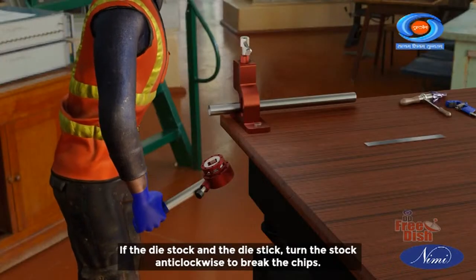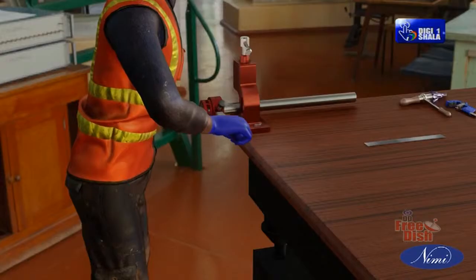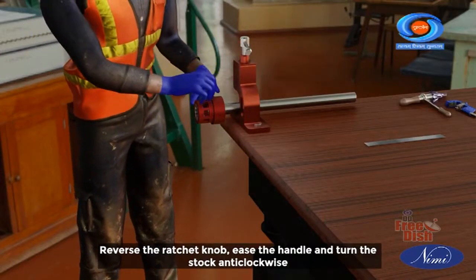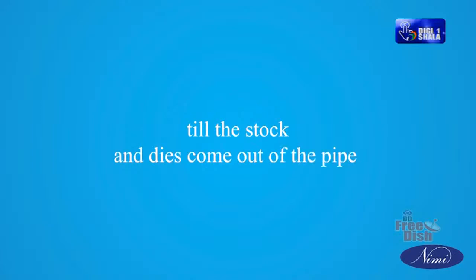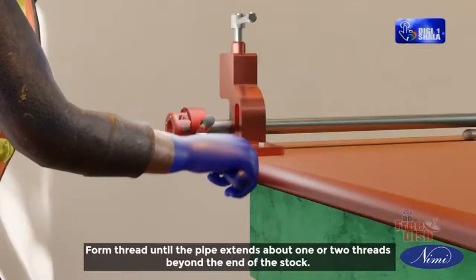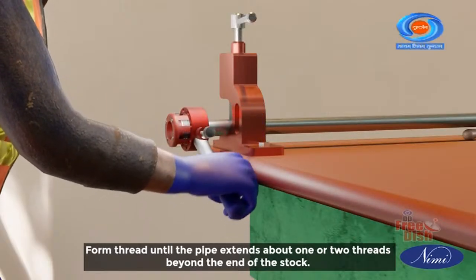If the die stock and the die stick, turn the stock anti-clockwise to break the chips. Reverse the ratchet knob, ease the handle, and turn the stock anti-clockwise till the stock and dies come out of the pipe. Clean the thread with a wire brush. Form thread until the pipe extends about 1 or 2 threads beyond the end of the stock.